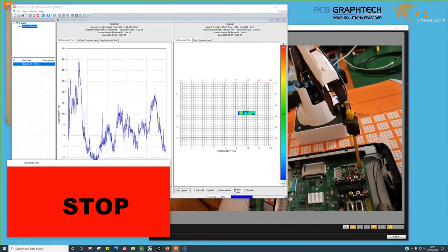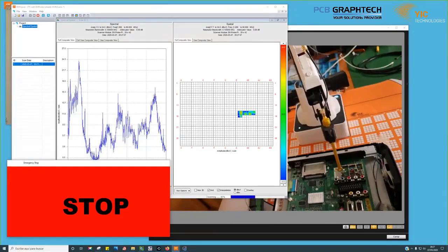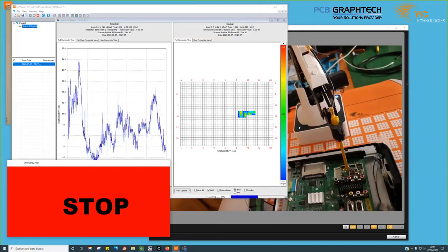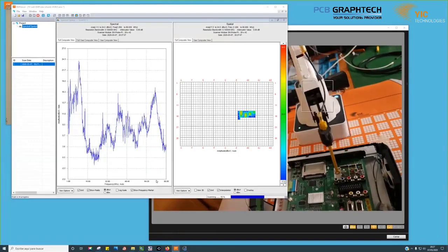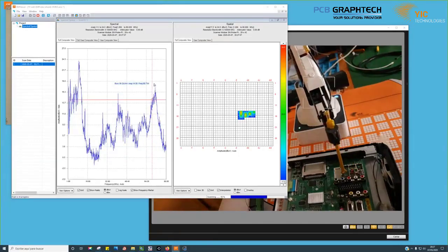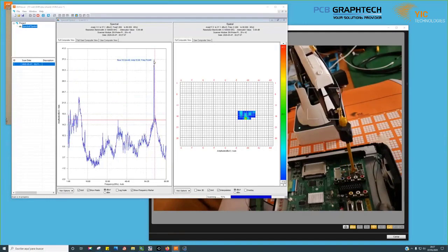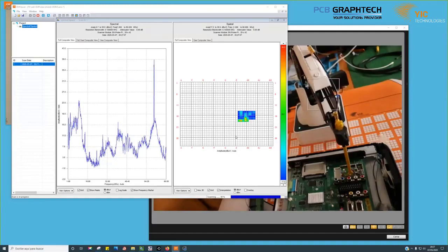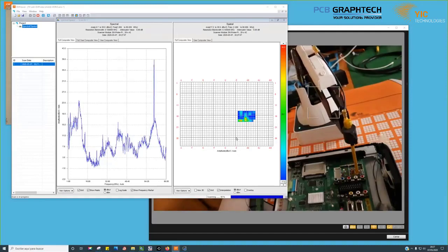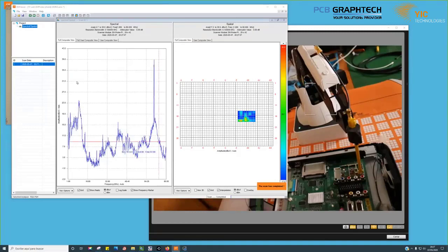When I was preparing this experiment in this area, there is a strong peak at 70 megahertz. You can see here the activity I was explaining. Here you can see that around 70 megahertz, there is a strong activity. You can see the peak I was explaining before, okay? And it's specifically in this area of the circuit. So this is the result. It's finished. Now let me go to the circuit, and I will introduce the shield. Where is the shield? It's here.